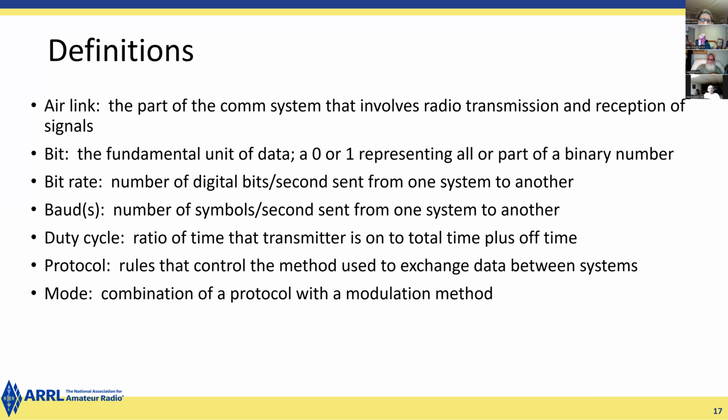For instance, the FT8 protocol uses 8 frequency shift keying. It uses any one of 8 audio frequencies, so that when you receive that audio tone, it could represent one of 8 different values, or 3 bits worth. Three binary bits can represent 8 different numbers. So you can send multiple bits per baud depending on the modulation method.